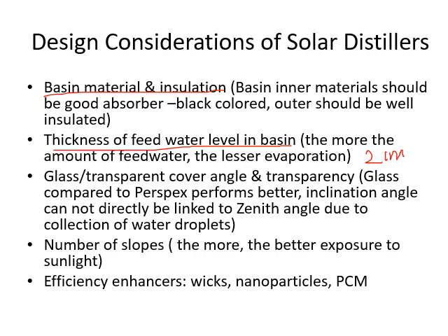Okay, so for the transparent cover, it has been investigated that glass actually gives you the better performance in terms of letting the sunlight in and creating the greenhouse effect. Plus, glass can work for a long time if it's not broken, without getting hazy or marred. The performance is not so good when we use perspex. Perspex will get scratched easily.